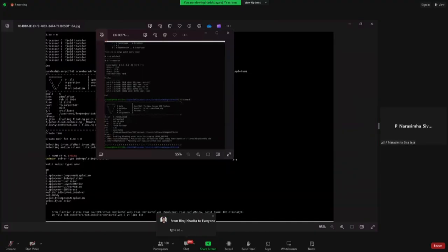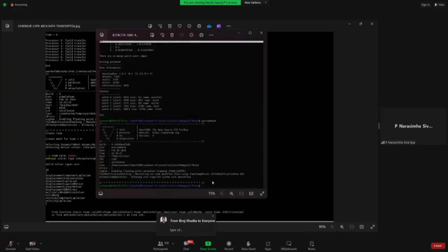No, actually, I changed the number of processes and we have 6 cores. I checked it. Okay. Actually, it is getting like no convergence criteria found, PIMPLE, no convergence criteria found. In the message, a lot of big message is there. Okay, I will drop it.